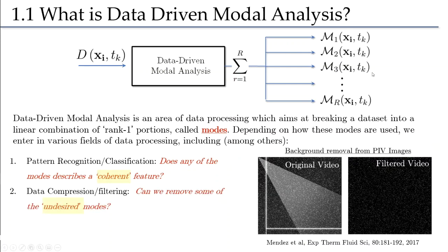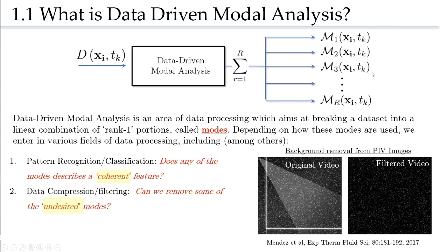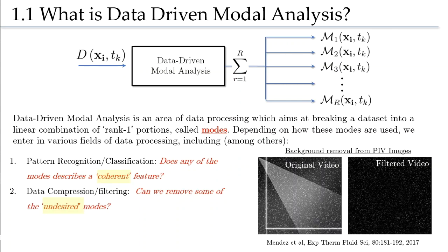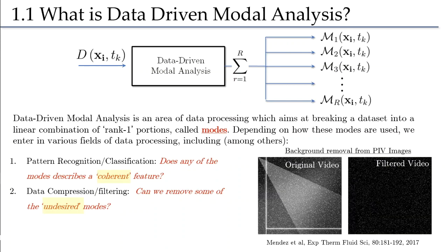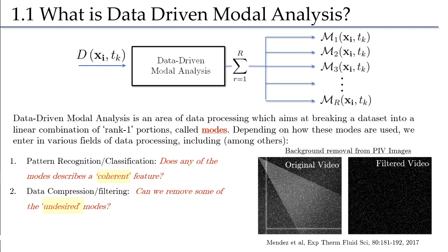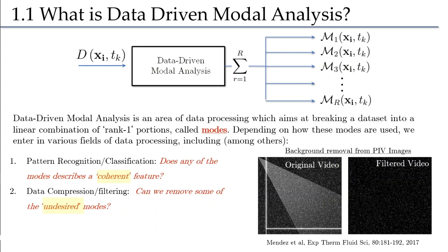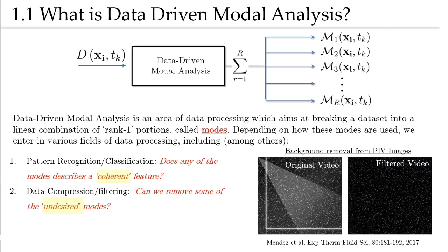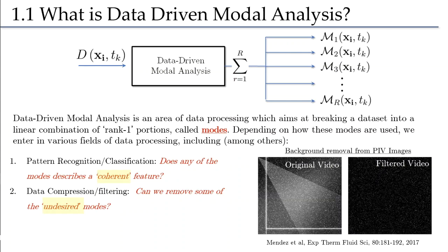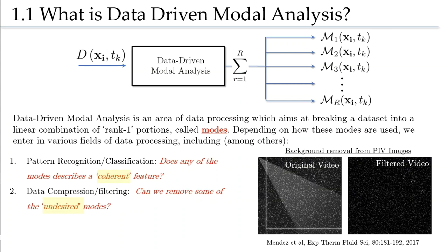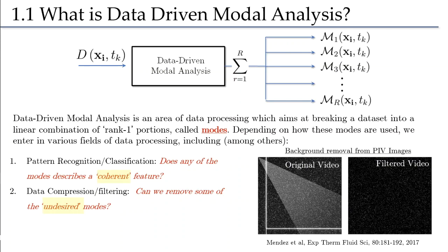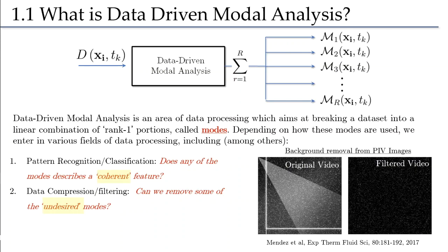Or you might wonder if some of the modes are irrelevant or maybe even associated with undesired features that you want to remove. By removing modes, you're doing data compression or filtering. Here I show you an example of such an application for video processing. In this work we have developed an algorithm for particle image velocimetry, which can do a great job in removing background noise such as reflections.